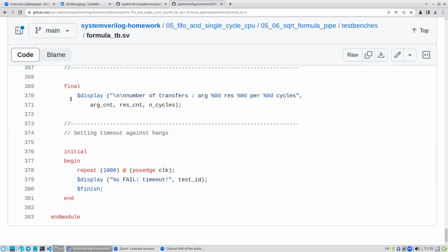There are a lot of open source tools, like Icarus, that can run our RTL in parallel with Python UVM. There is an open spec that can be run in cocotb, which is the same type of thing as UVM, but it has a Python version that can make life easier for the open source stuff.